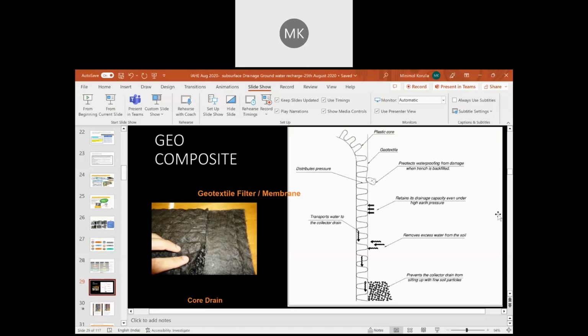Normally these woven geotextiles are used either as reinforcement, which gives strength, or as confinement, as in geotextile tubes or geotextile bags used in coastal erosion or coastal applications, for dredging applications or waste disposal. But we are more thinking about non-woven geotextile.